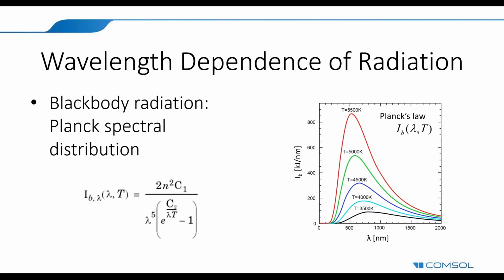So for high temperature, we get short wavelengths, and for lower temperature, we get larger wavelengths. So just this to say that depending on the surface temperature for black bodies, we get different spectral distribution. And then if we consider non-ideal black bodies, but gray bodies, for example, then they have a surface emissivity that can be wavelength dependent. So depending if radiation is coming from a hot source or a moderate source, it may behave differently depending on the surface property.